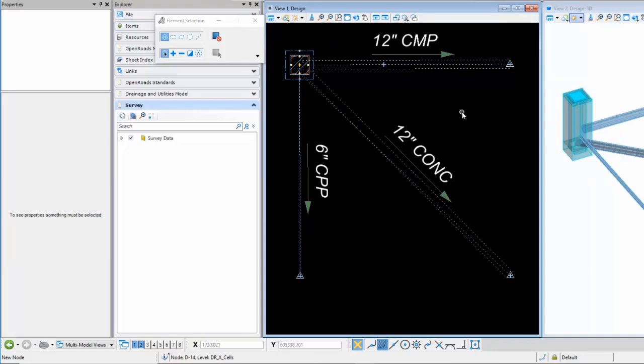I didn't review my survey data to see what those dip values were and what those elevations should be. So what I'm thinking about doing on the Drainage VBA app, if you store attributes on the structure, I could write a report that would just read the structure, get its attributes, and then report the elevations and everything for each of the pipes that have a P1, P2, P3, 4, and 5 attribute. So if you think that type of report might be useful, just let me know, and I'll look into seeing what I can do to possibly write a report from the fieldbook file.